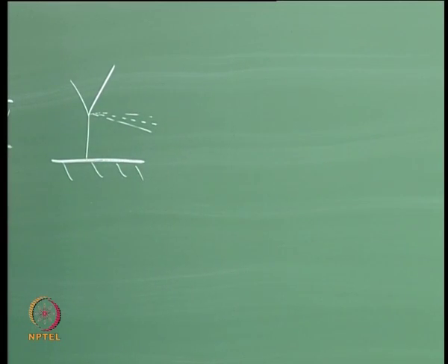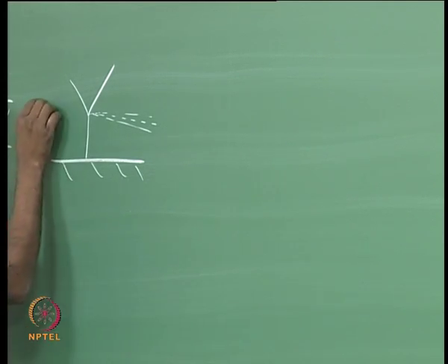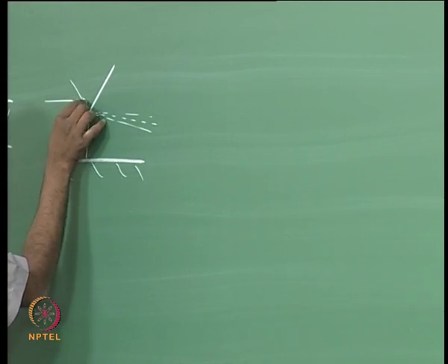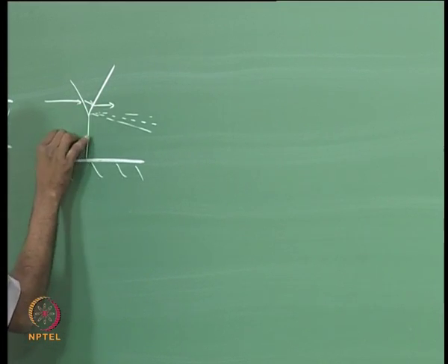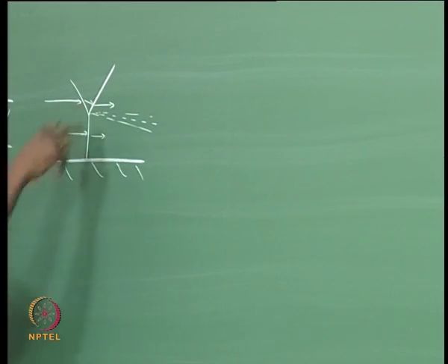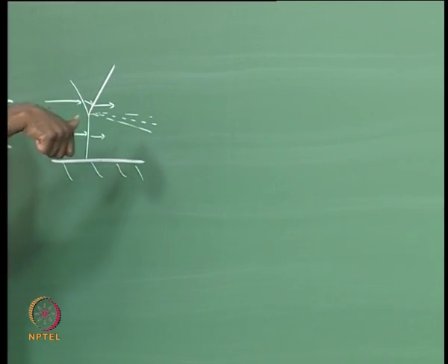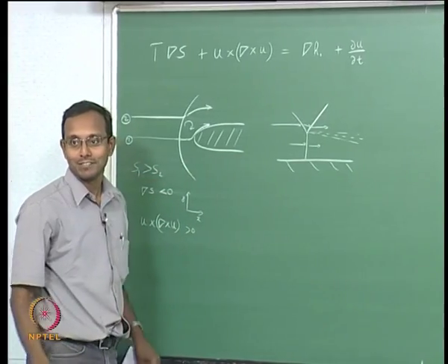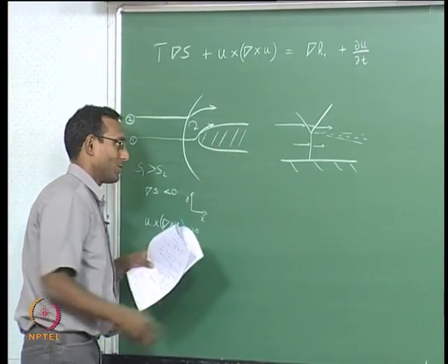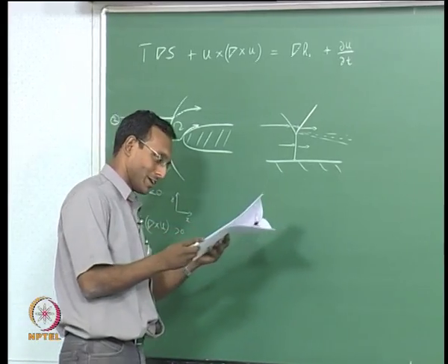What is happening inside there? It is having vorticity. If there is a slip, that means there is a gradient in velocity, right? Which one will go higher? Which one will have higher velocity? Upper one will have higher velocity. So I am again going to have negative vorticity. I can go through the same explanation, it will give you the exact same answer finally. You can go through this problem also and get yourself convinced.